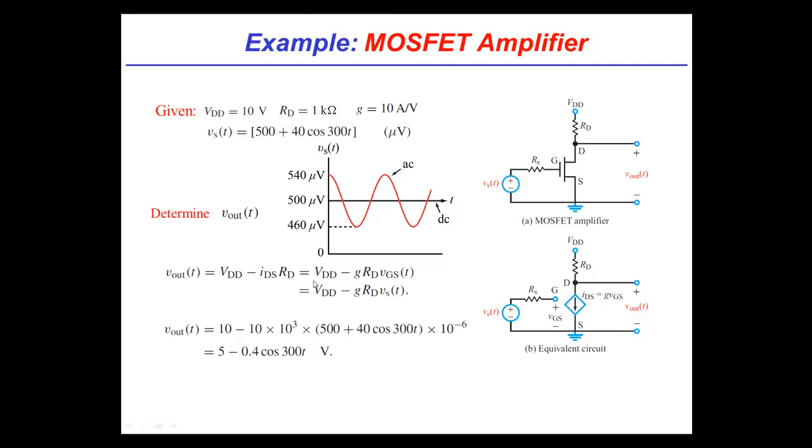But I guess that in the end, the trick was that you keep your VDS pinned right here, right at some fixed DC value, and then this small wiggle around it. Correct. So this is what we said about cheating. We essentially ensure that we always keep it at a VDS that's large enough that this model makes sense.